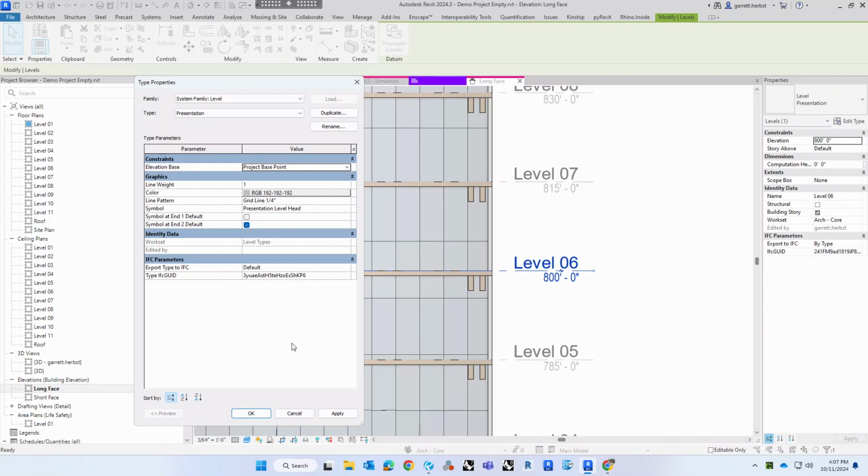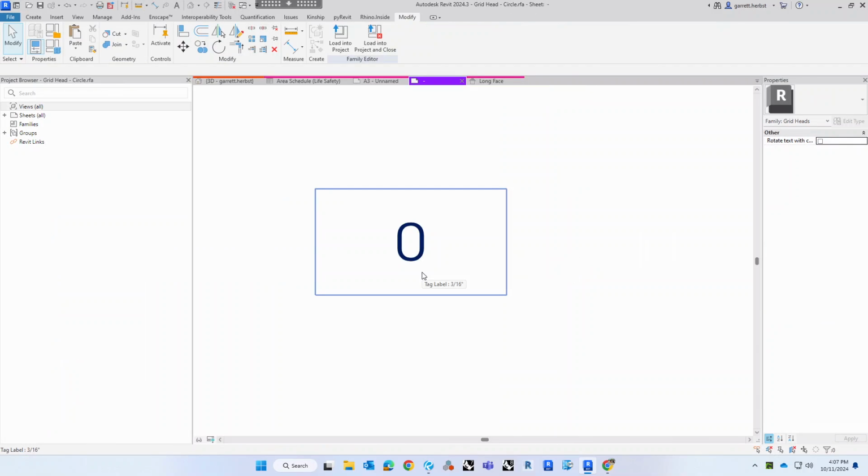The one other thing, and this is true for a lot. Oh, this is what I was going to actually say for the title block. So you can create your own title blocks. That's how we've created all of ours. That's how everybody creates theirs, is they go into the sheet family, and then you can add different parts and pieces to them.